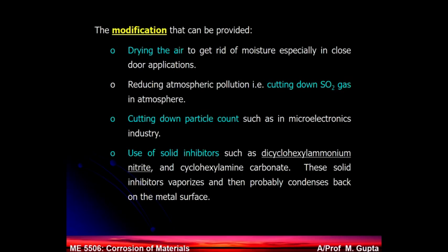Now, what they did not realize is when the aircon systems are switched off for a longer time, the humidity starts to come in and water starts to condense on the different joints of the machine, and they start seeing corrosion at the joints, wherever two metals are combining, wherever there are places where the water can accumulate. So the corrosion started.